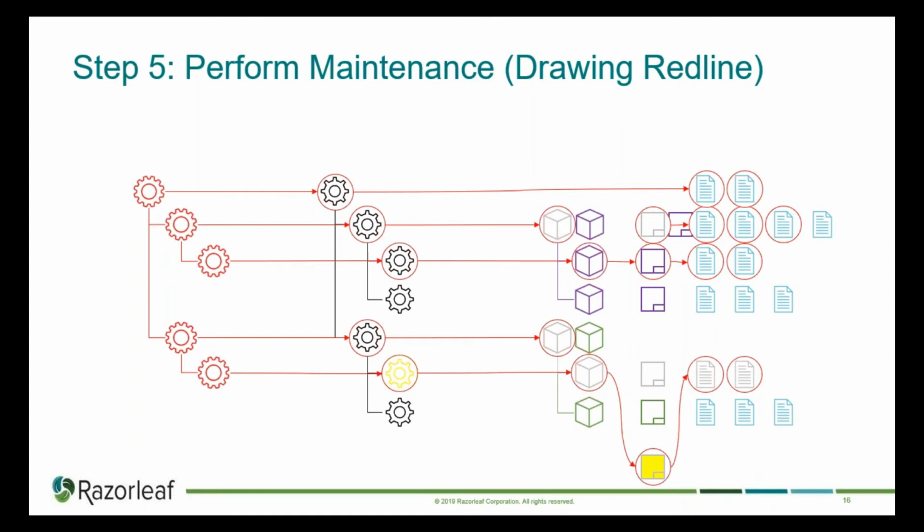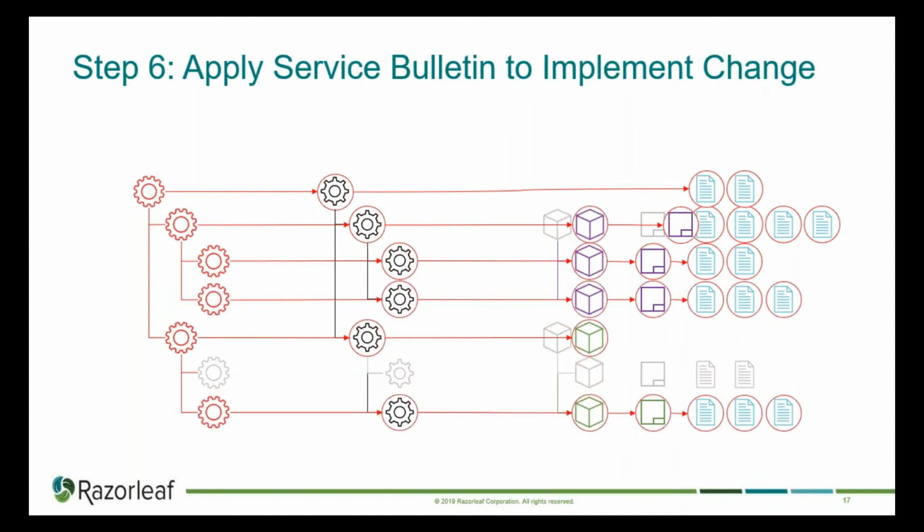They needed to fix it, repair it, and they need to redline the drawings for what that was, again, so that they'd know that specific one had that damage, had that repair. So all of this is the sort of stuff they had to keep track of and then maintain it as service bulletins were applied, right? So as changes to their fleet came out, because we've got an upgrade, they need to incorporate that and update the bills of material for the as maintained bills as they went.